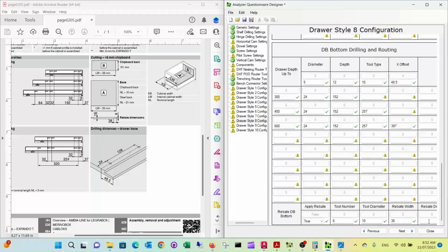And what I found with the rebate depth, it tells you 8 millimeter, but usually the boards they vary a little bit, so we usually use 16.3 for our specification because that's the maximum size that the board thickness usually is.